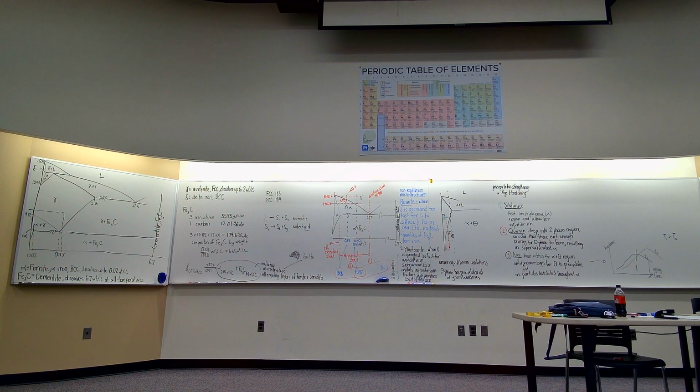Hardenability. And so it turns out that 4140 steel, that third steel that we're dealing with, is a high hardenability steel. Not necessarily a high hardness, but a high hardenability. So this lab experiment is about things that affect the hardness or strength of a steel and things that affect the hardenability of a steel. Okay.